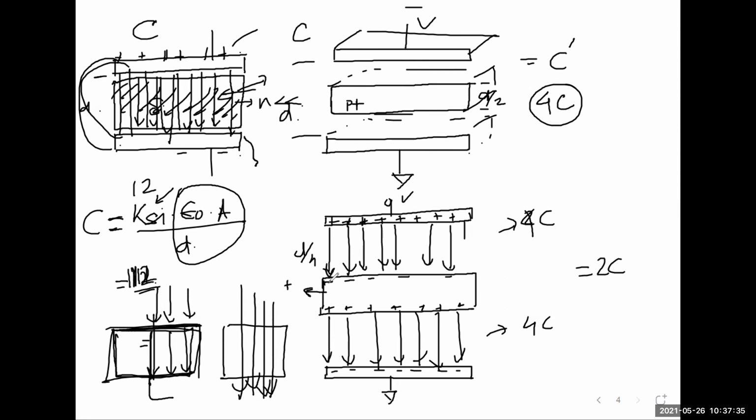So this electric field will drive away the holes because they're free carriers and leave a negative charge, which is an immobile charge behind. And the positive end will go here to this place, and that will start the electric field from here to here. There cannot be any electric field inside this.